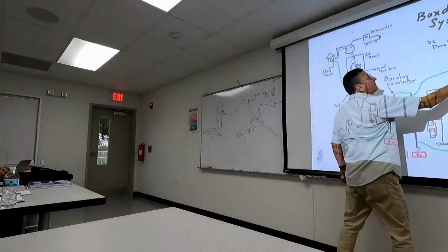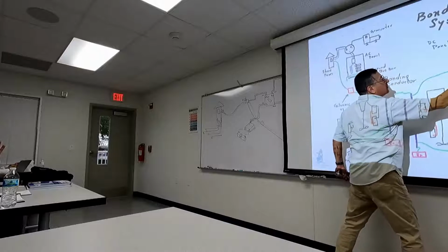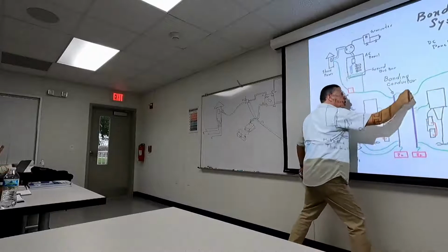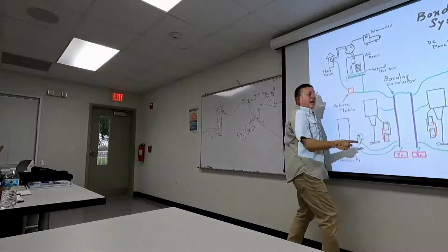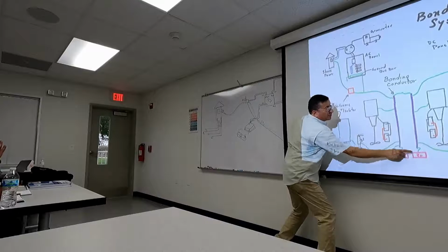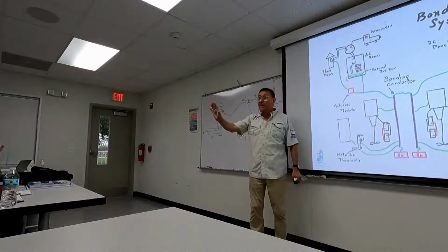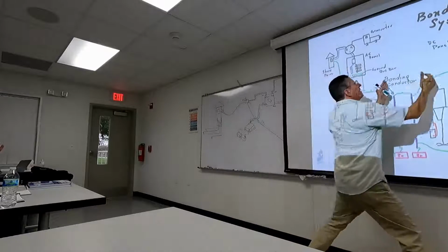We are going to check the DC panel. You remember? The positive enters the main breaker, small breakers, the DC negative bus bar. The negative bus bar is also connected with the bonding system, the bonding conductor, and the bonding conductor is externally connected with the zincs. It's clear? Right now this is the boat. I have an AC panel, I have a DC panel.